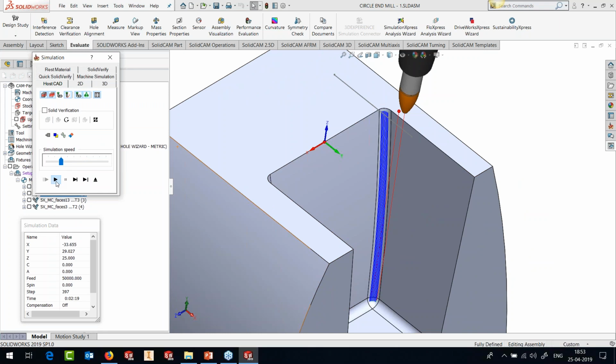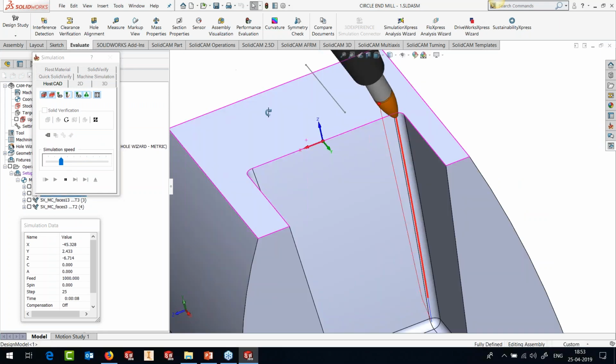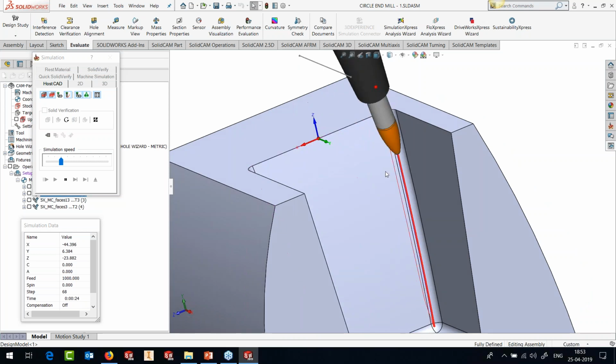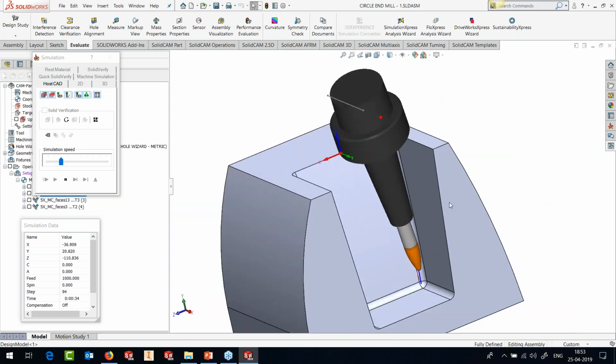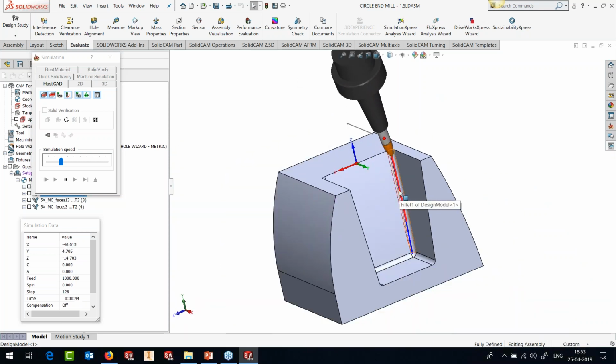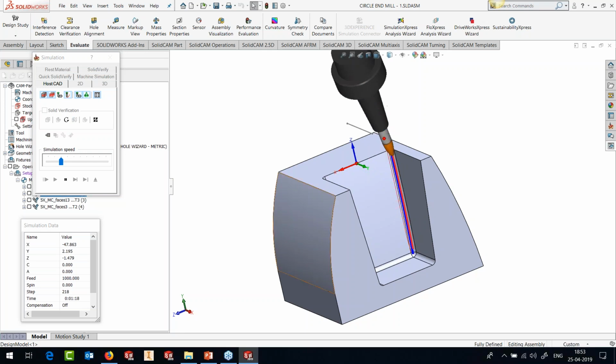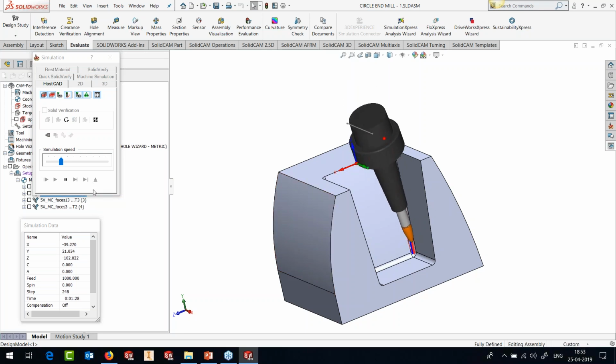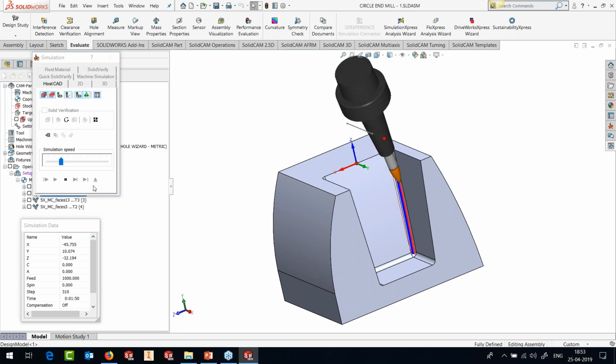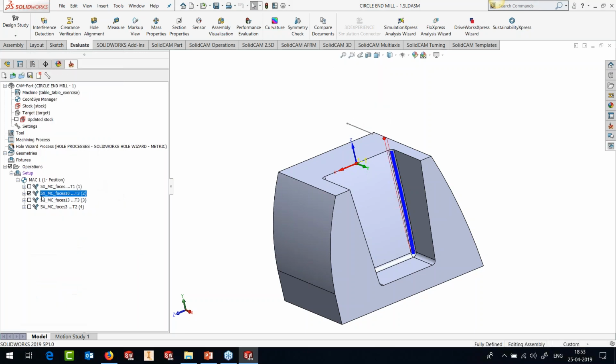Let's reduce the speed. And this is how it does. And here again, we have used the auto tilt mechanism. Here you can see that we're using the tip of the tool. So we are using all the portions of the tool to machine also the fillets. Okay, and in the automatic tilting, the software takes care of avoiding the collisions with the holder and the part around it.